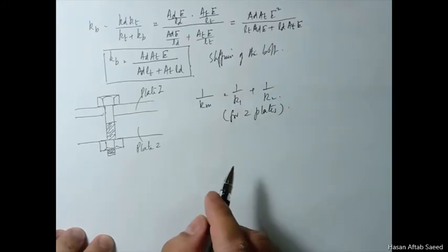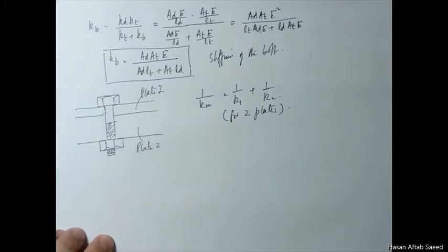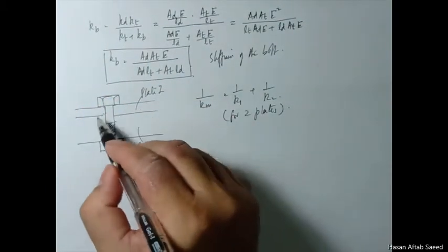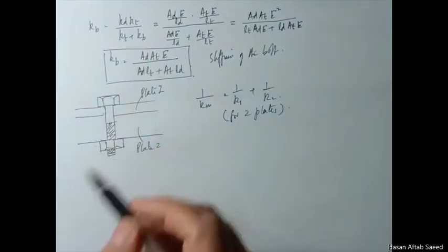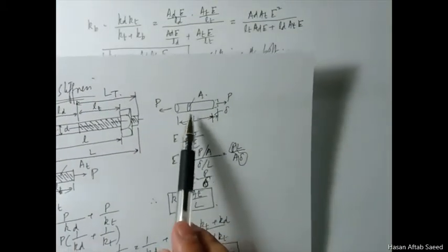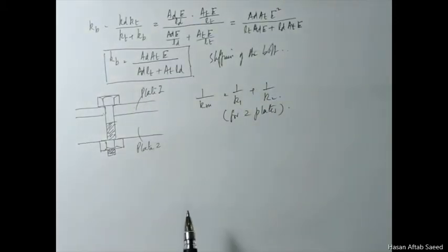Now, this would have been equally simple as we just saw the case with the bolt, but actually this is slightly more complicated. The good thing about the bolt was, when you tightened this, the bolt went into tension, and these 2 plates came under compression. The whole area, threaded area here, unthreaded area here, comes under tension.